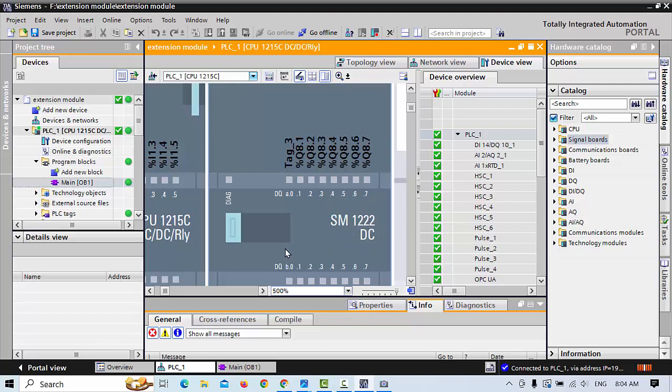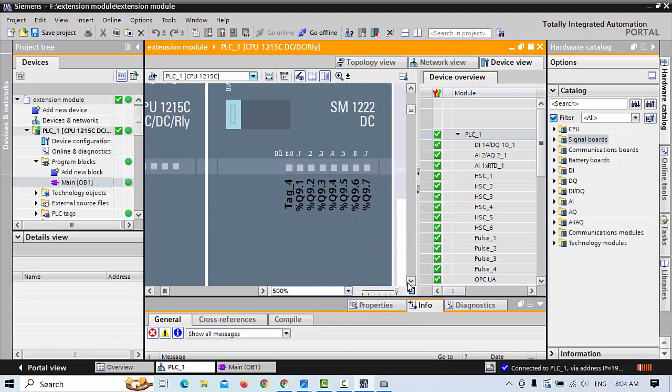In common you have to choose plus voltage and minus voltage, and the plus voltage you have to give to an outside relay. In external hardware you can use one relay, and this gives 24 volts to your relay, and your relay will be energized.